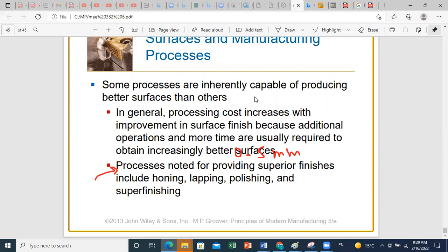The idea is that when you have very small grains, of the order of 10 to 50 micrometers, and rub them on the surface, this will smoothen it and reduce the roughness of your surface. The smaller the grains used for the honing stone, the better the smoothness you can reach.